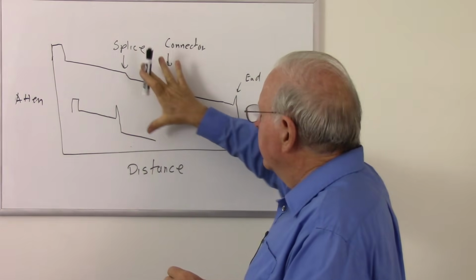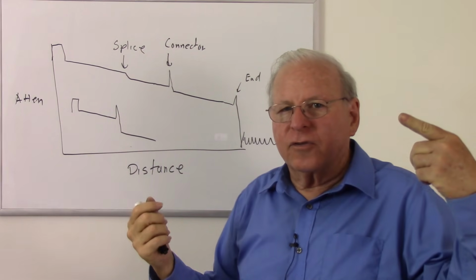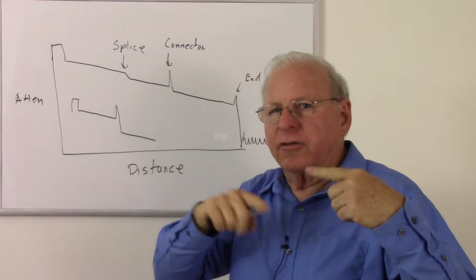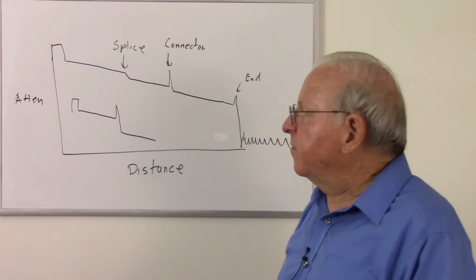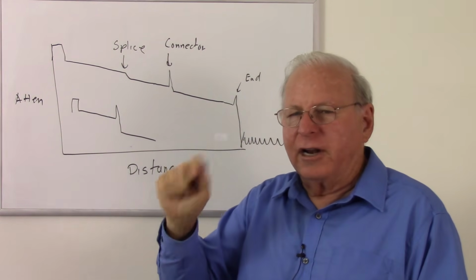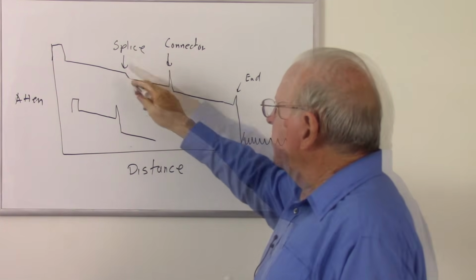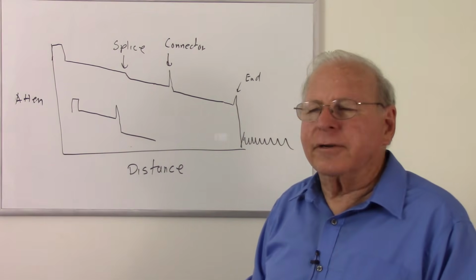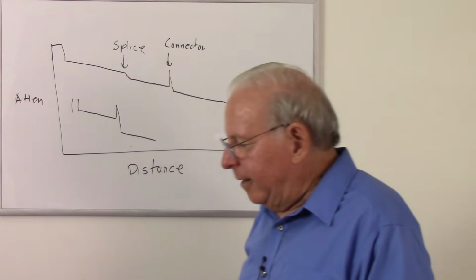It can tell us how much loss we have, but it's not as good as a source and meter to test. So if you're testing for actual optical loss, you need to do the source and meter. The OTDR is really for fault finding to make sure that everything looks good. So you get your installation, you stick the OTDR on each cable, see a good connection on each one, not too much loss at our splices and connectors, we have a good to go installation. So that's the OTDR. So finally, safety.